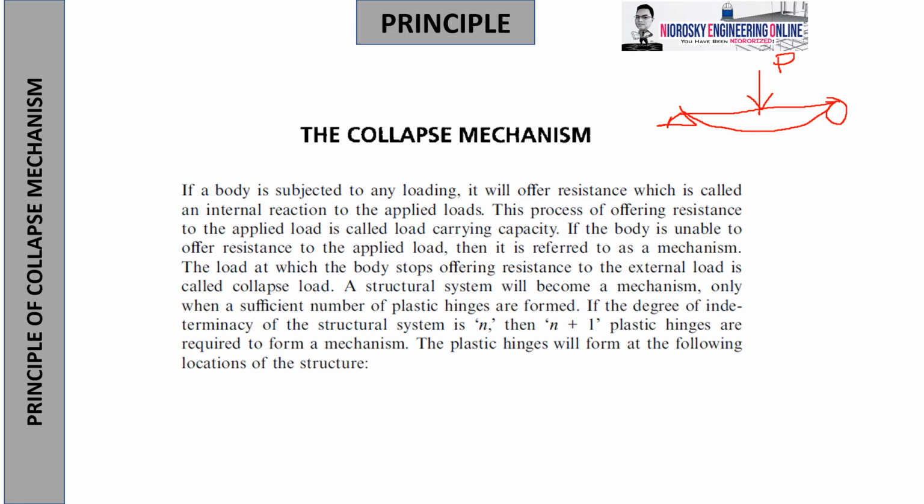And as you increase the load P gradually, of course the deflection will gradually increase. In concrete, as you increase the load, cracks may happen on the tension side, and creep will most likely happen on the compression side, and then finally failure. But in steel, there will be such a time that as you increase and increase the load, the final output will be larger than the load.